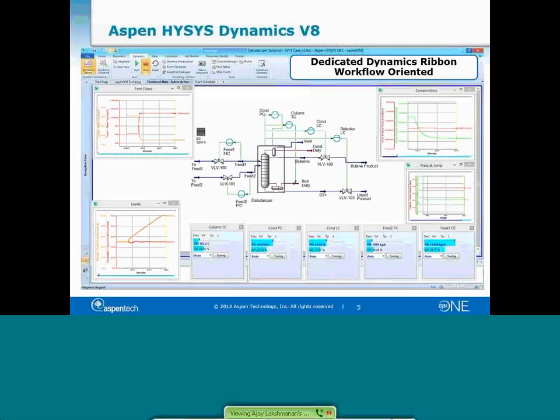It's just a checklist. You should use it as such, as a checklist. Depending upon your modeling requirements, you may choose to take its suggestions or ignore its suggestions. You'll see during today's demo that I will be ignoring some of those suggestions because I've set up my model differently, the way I want to do so. Then there's the integrator settings, and the runtime buttons that are required. There are several modeling options, all of which bring you into tools that are required for dynamics modeling, the control manager, faceplates, etc.